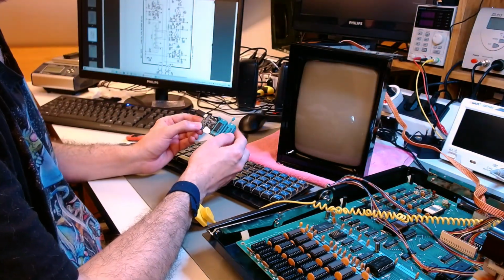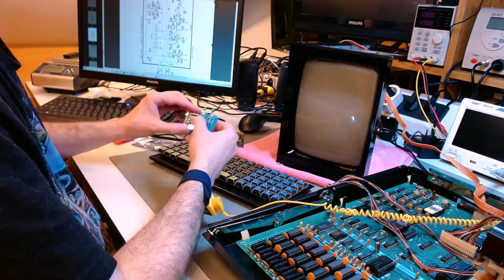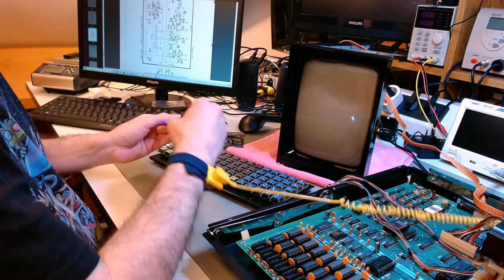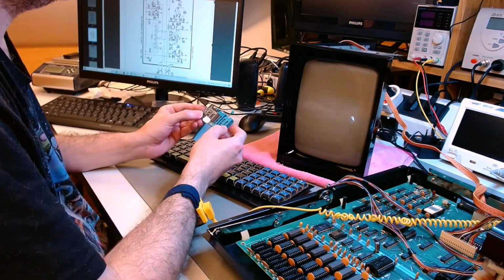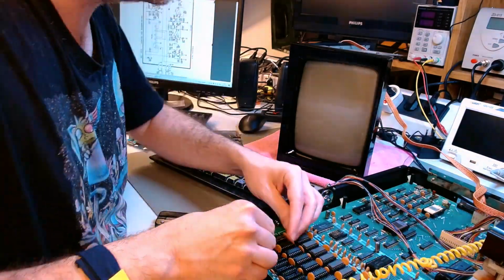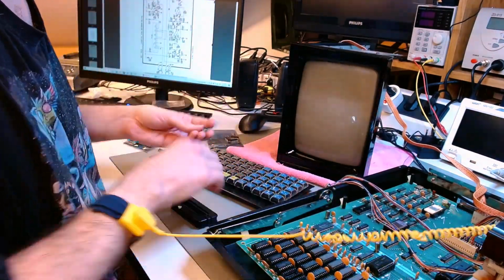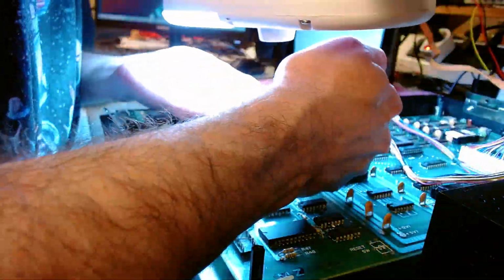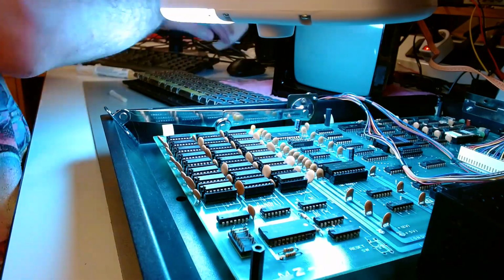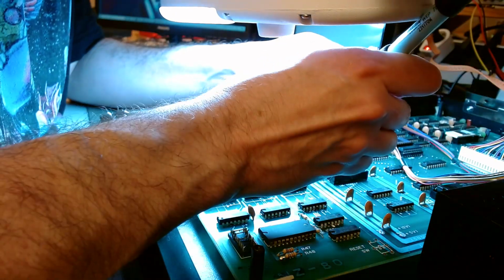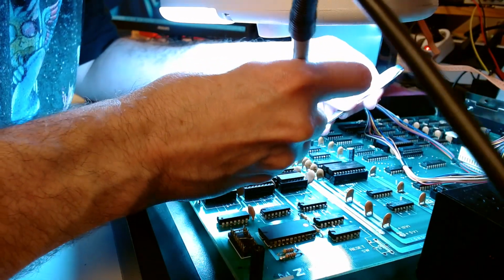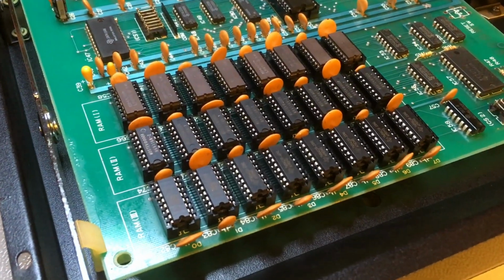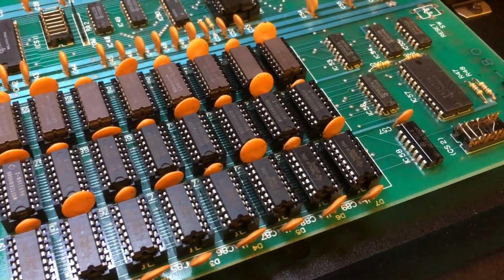So as it happens, I just got a new batch of 4116s, so I'm testing them all thoroughly with my tester. And if I'm satisfied they're all okay, then I start putting them back on the board after straightening the pins, as you see. And after I reconstitute that third bank of RAM, I have to readjust the jumpers to reconfigure the machine for 48K. That's what I'm doing now. And that's the result. Now all 3 banks are fully loaded with working RAM chips.